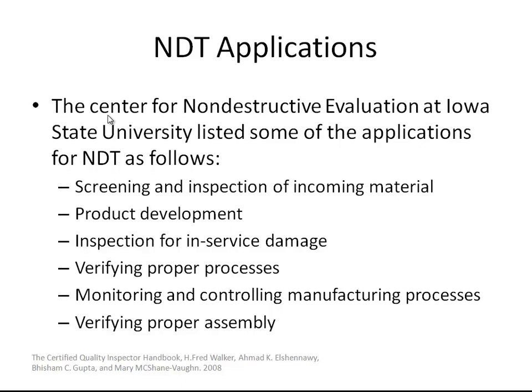So you don't have to put loads like 300, 400, 500 pounds until it breaks to make sure that it will withstand that, but you can say it has been tested up to 200 pounds in your report when you do that for your product or in the product development that you have. And this is just an example that I'm giving you here for the inspection or the testing that you might do, and it can be non-destructive testing in this case.